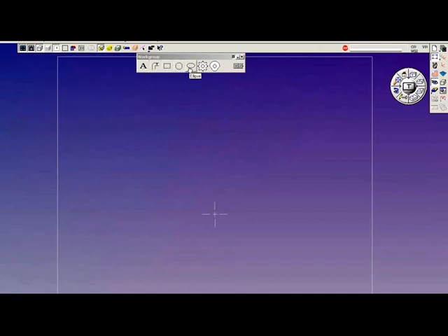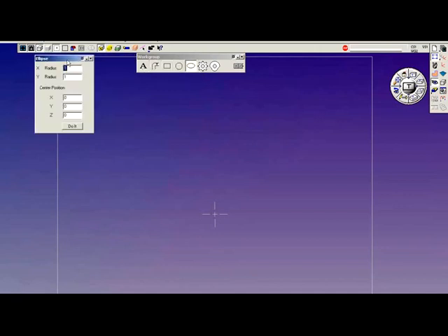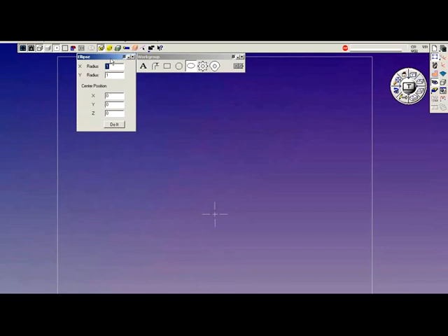All right, the next tile is the ellipse. The ellipse, same rule applies as polygons and boxes. We're dealing with the center position. The x radius, 2 inches, y radius, 1 inch. Do it. Generates an ellipse. I'm going to turn on labels. Notice that we see a B1. An ellipse is not a circle or an arc. An ellipse is a B-spline.